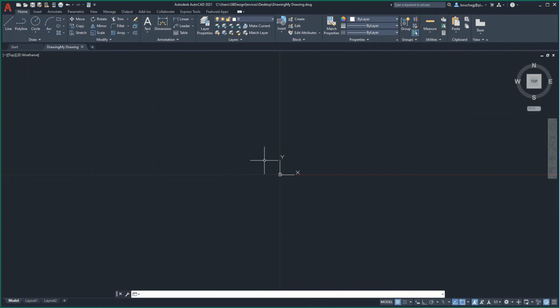If we created our personal .dwt drawing template file at this point, we would need and want to update this .dwt template file each time we make a future global user setting change. We don't always remember to do this, so waiting is a temporary and better option.